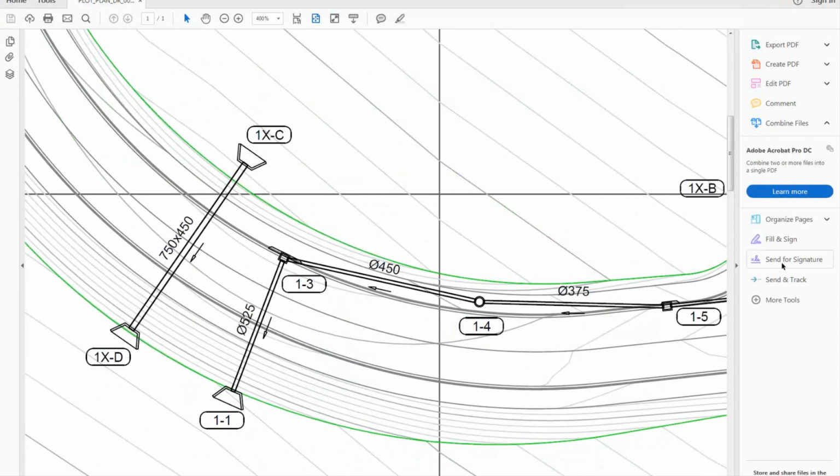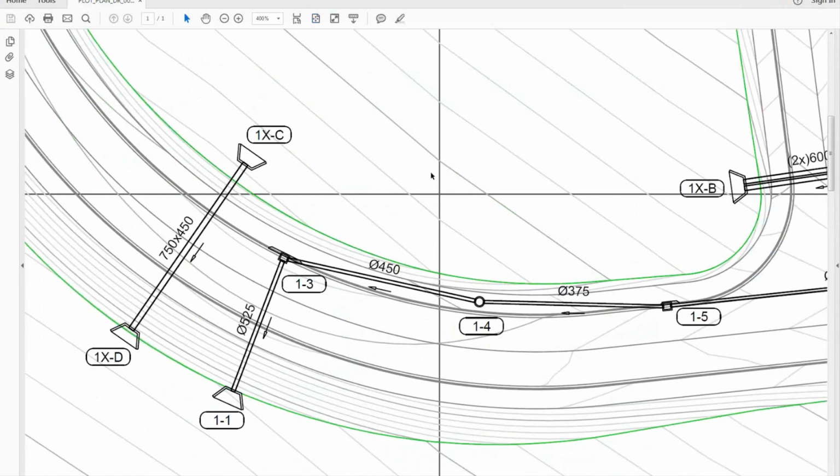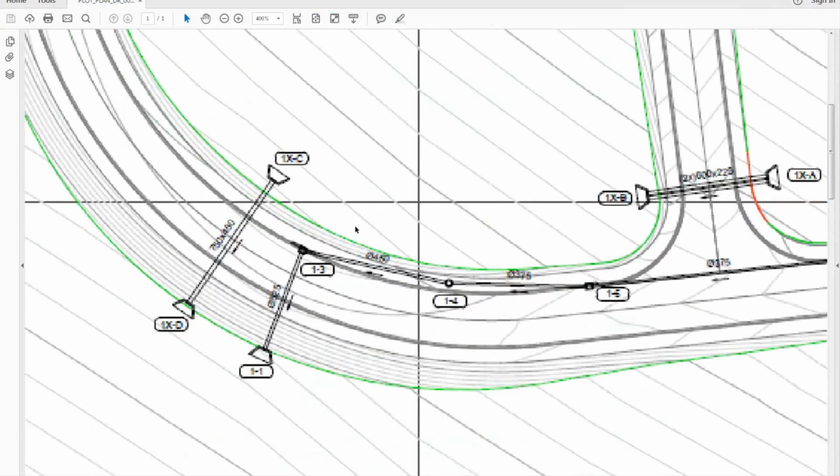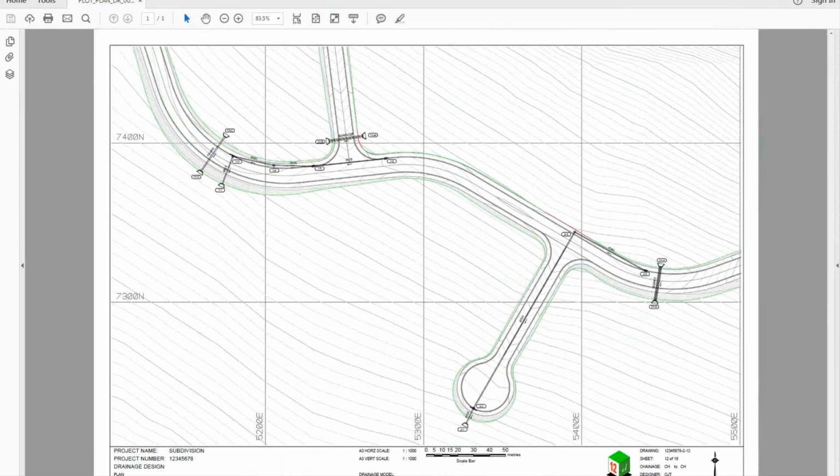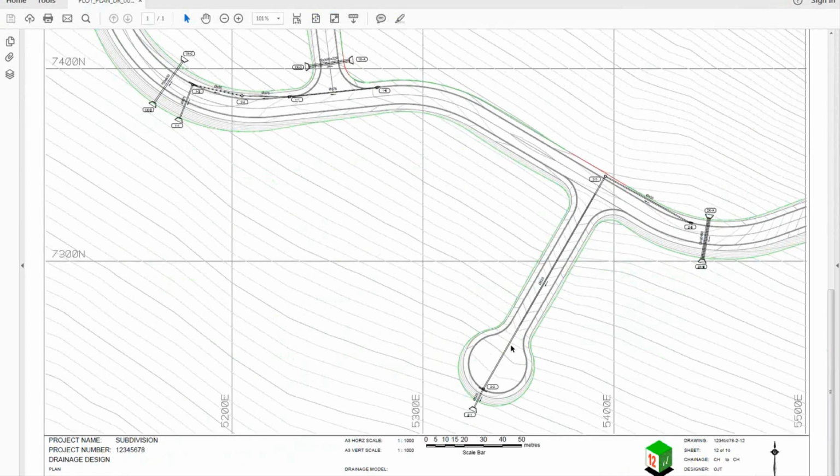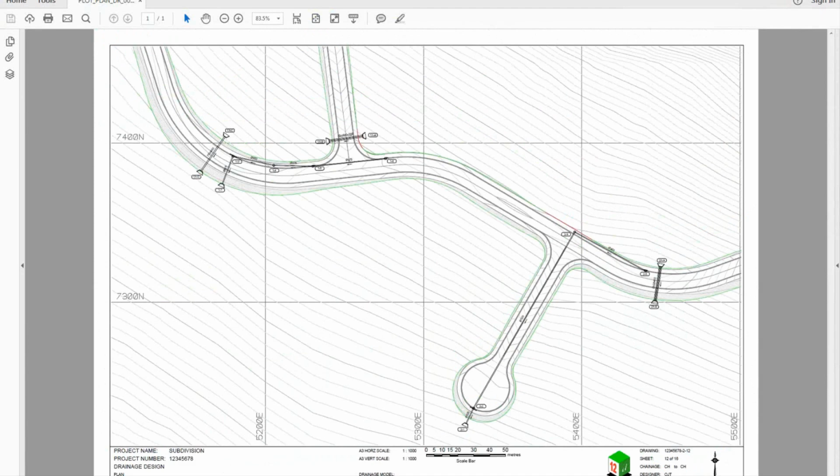The annotations we see here for the drainage line are produced by one of the drainage plan PPFs that I mentioned earlier, the one that's intended for final design plans. It's only showing the structure names in bubbles and the pipe sizes and the flow arrows, and gives you all the symbols and all of that. But a lot of new features have gone into the drainage plan plot that's beyond the scope of today's topic. That might be a separate webinar topic for the future. And because it's going through a drawing register, all the drawing numbers are appearing on the sheet there. This one's set up with a scale bar and a north arrow and all that sort of thing as well.